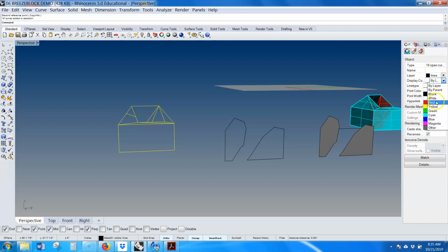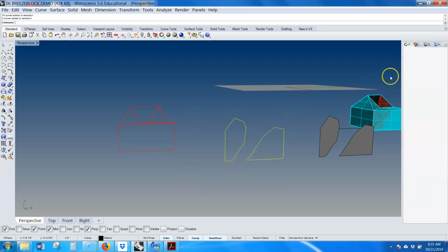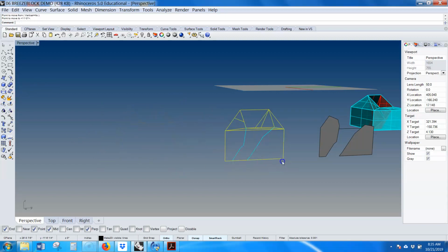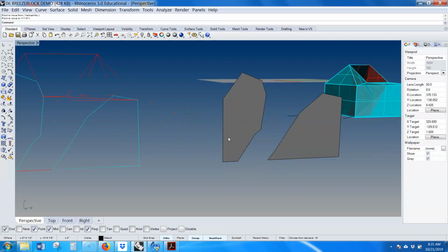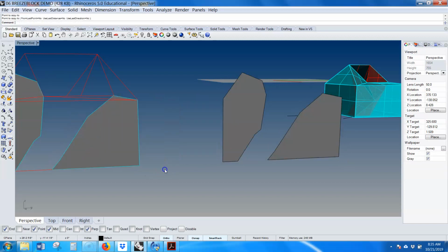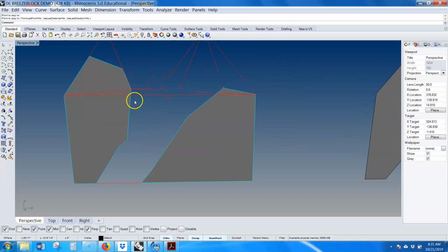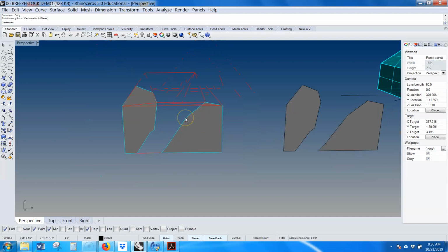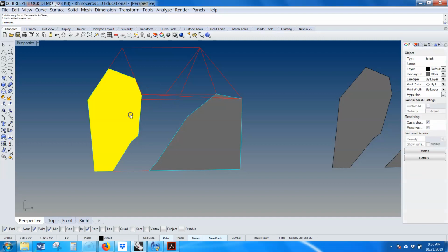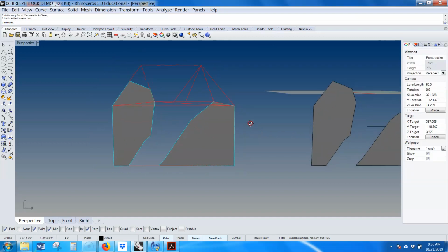And again, remember your elevations and sections, your cut lines are always your thickest lines, right? So give that a certain line weight. We'll give this a different line weight, and we'll group it. And then maybe we add these hatches to really show what's being hatched. I really want to push this to the back. This kind of gets it. We may want to put this hatch in front of this when we lay it out. But that's a little better.